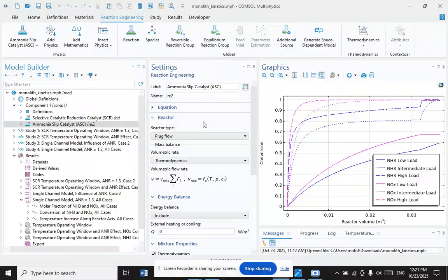The surface coverage of ammonia can be related to the fluid phase concentration by assuming that ammonia desorption and adsorption are in equilibrium, with a Langmuir-Hinshelwood mechanism based on this assumption. Global rate expressions can be derived.